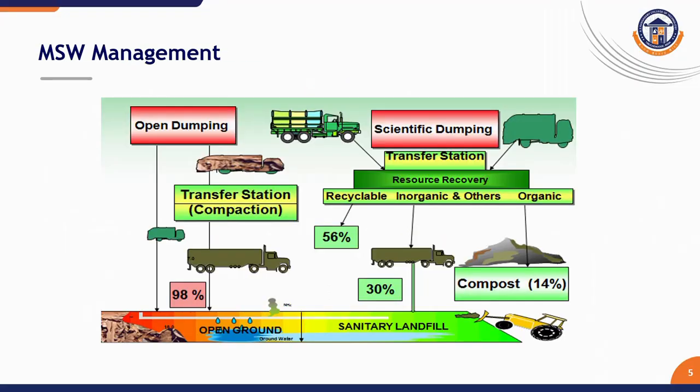The picture clearly shows municipal solid waste management. So first one is the waste being dumped in an open area, then collected by vehicle through a transfer station. It is 98%. And second one is scientific dumping. The waste is collected and recyclable, inorganic and other organic materials are separated. And finally, it is disposed into a sanitary landfill.